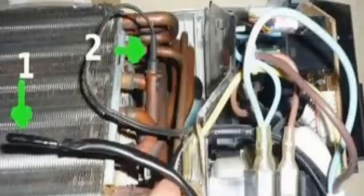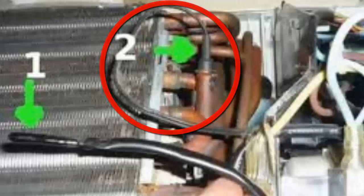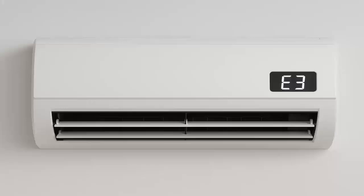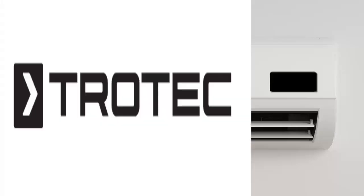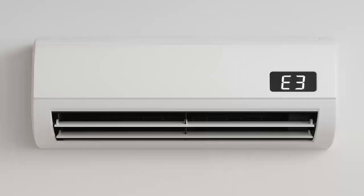Third meaning of code E3. Issues with indoor temperature sensors. This code may be related to the pipe sensor, evaporator tubing, or the ambient air sensor. The brands where this case appears include Trotec, Fujitsu.